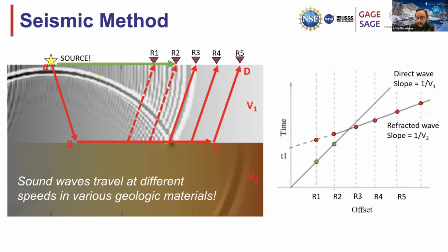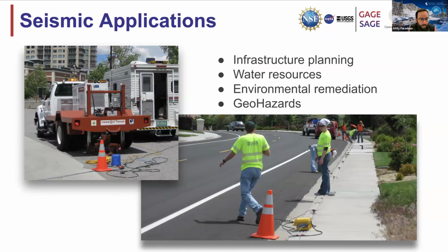And so the whole point of seismic refraction data analysis is to figure out the depth to that faster layer and the velocities of the top layer and the lower layer, and use that to interpret things like how deep the bedrock is, or where the water table is, or what the material properties of the different materials are, which can be used for geologic interpretation, geophysical experiments, or environmental studies. Next slide, please. So, some examples of applications.